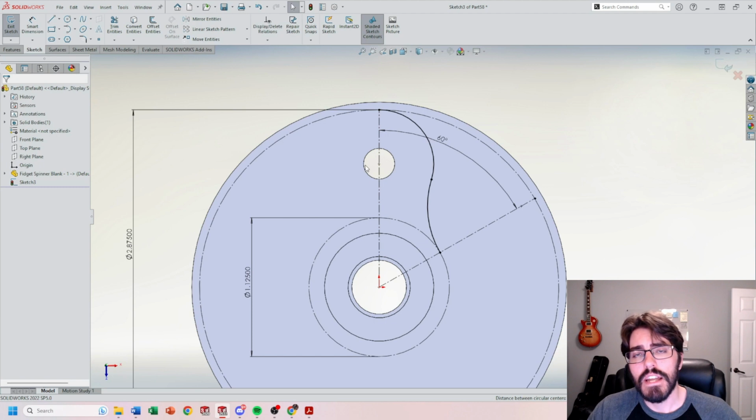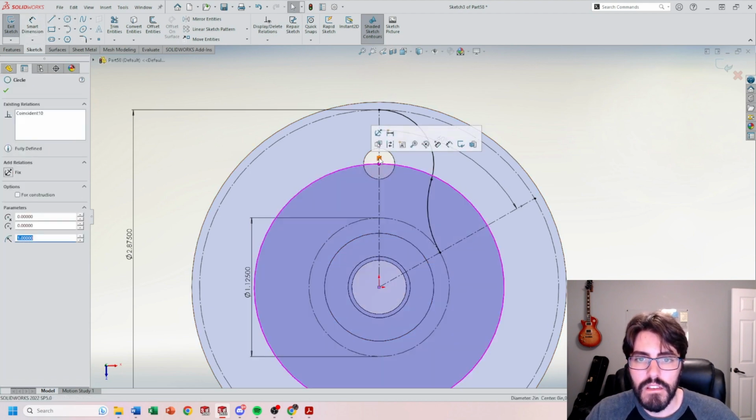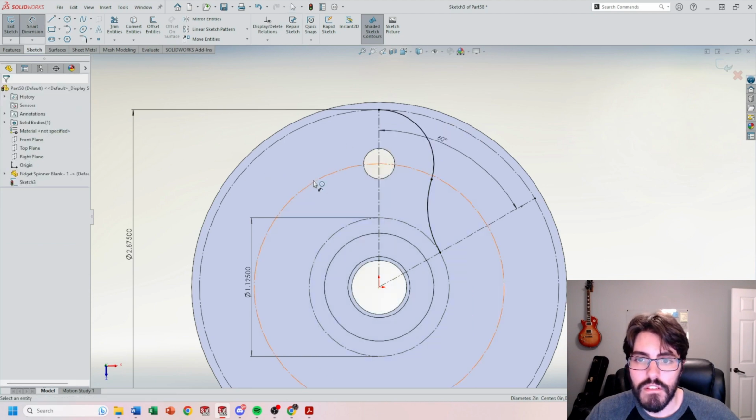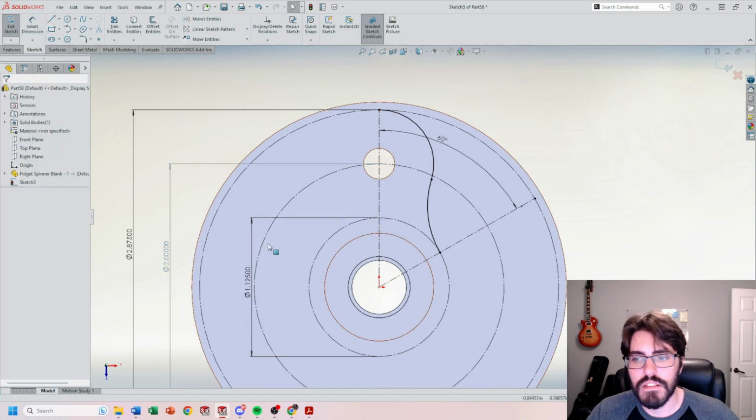Now again, if you didn't have this through hole to take advantage of, you would have to draw the diameter of it. And I'll just show you really quick if you're doing this on your own, that value there is 2 inches, not 2.25 like I said before, but that's a 2-inch reference, and you would just have to draw these arcs accordingly.